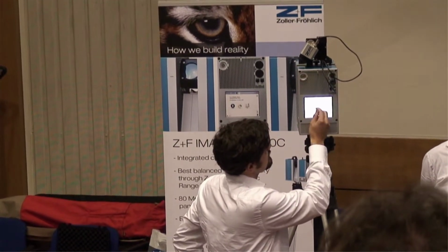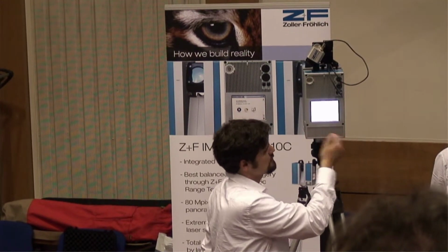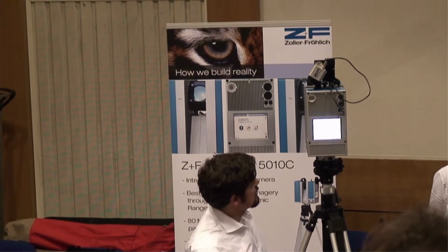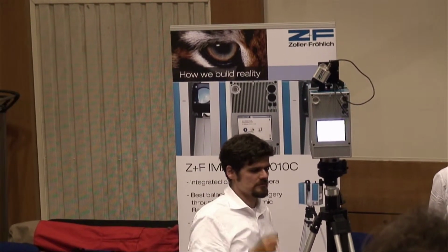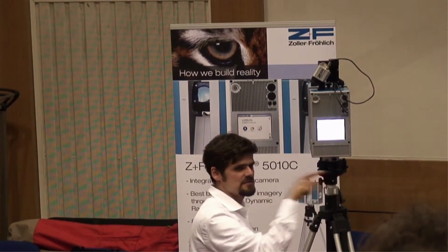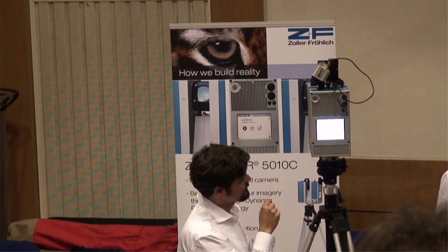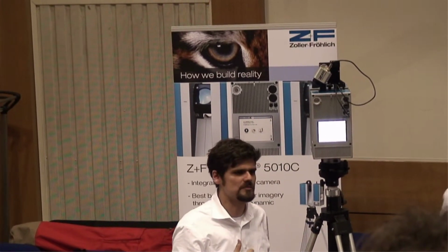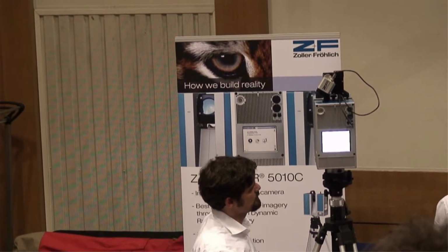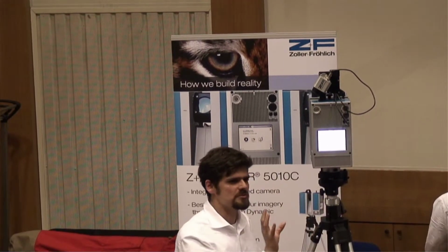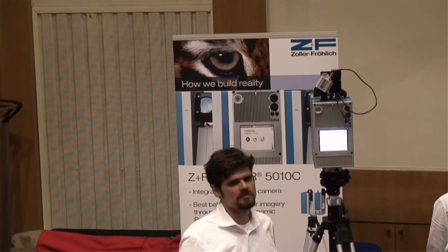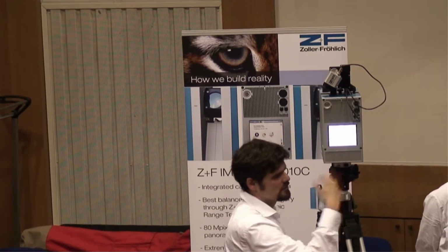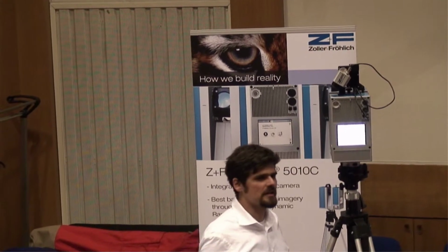Normally, our standard setting is a high resolution with normal quality. Normal quality is the second setting on the quality scale. That is about a resolution of 6 millimeters at 10 meters distance. For the normal speed, I'm not sure how many points that acquires now, probably around 250,000 points per second. The entire scan, just for the geometry, takes about 30 minutes and 20 seconds. You can go to less quality or to a lower resolution to speed things up. The quickest scan is 25 seconds.